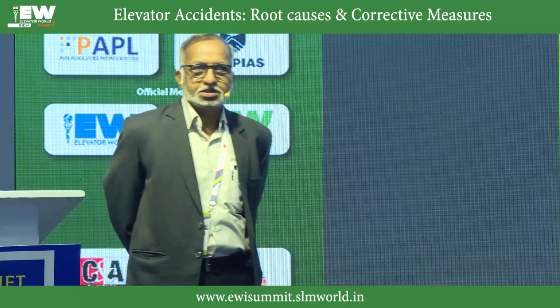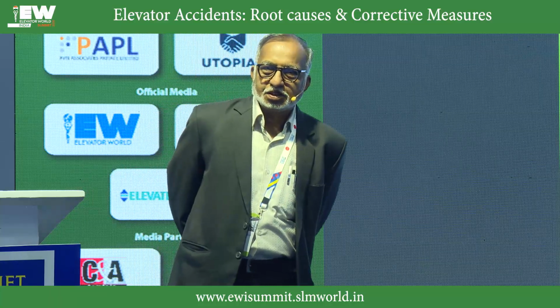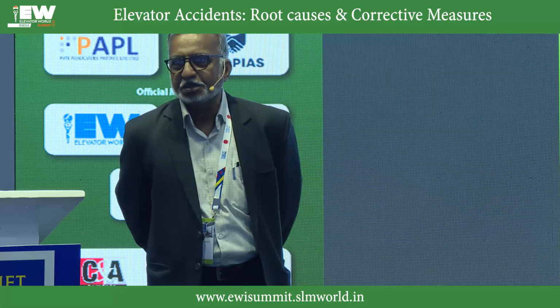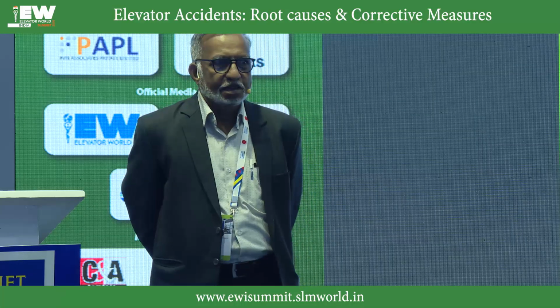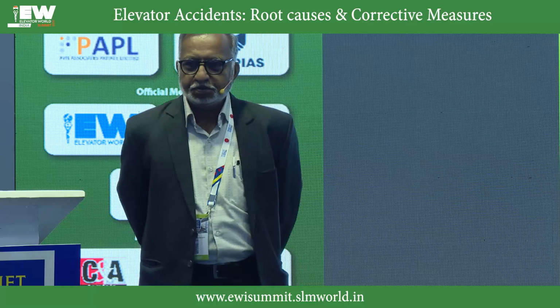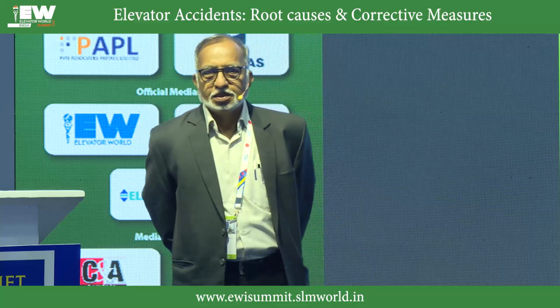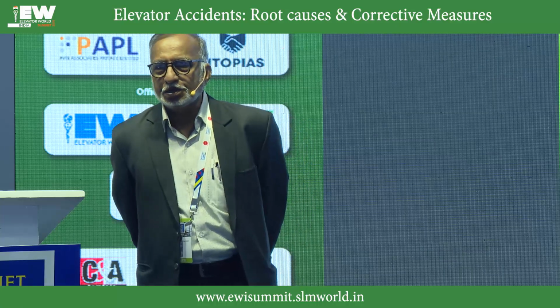Now, this is an accident where there is great negligence of the user and service provider. There is a pulley on the counterweight. That counterweight pulley was not properly oiled, and greasing was not done to the pulley bearing.